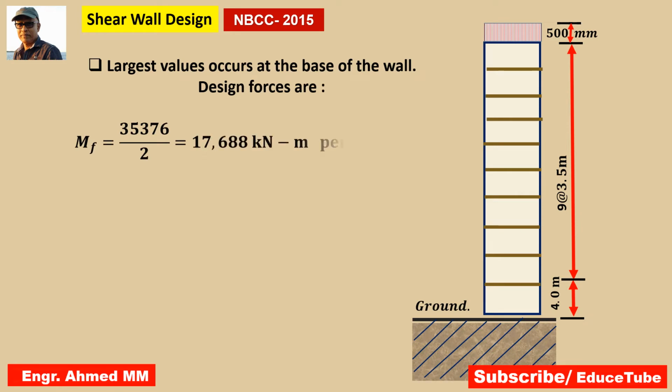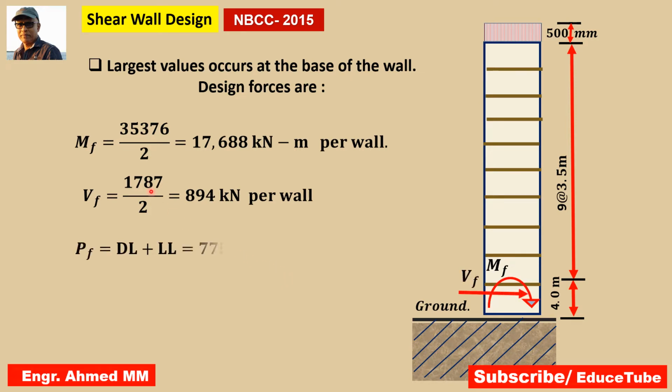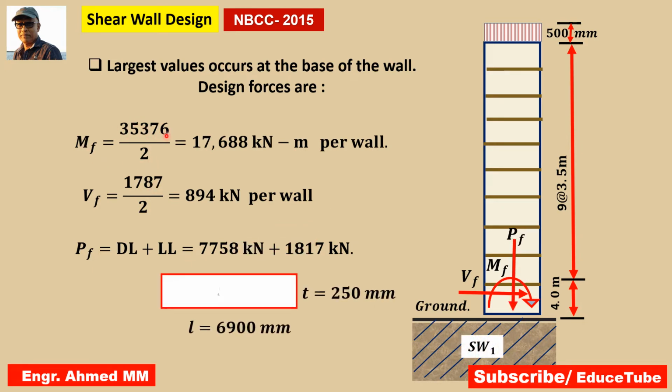So what I'm doing, this is the shear wall. As I said, I brought some values from the previous two slides. One was 35,376. That was for two walls, so it will be divided by 2, giving 17,688 kilonewton meter per wall. This is moment, on the first floor, this MF.